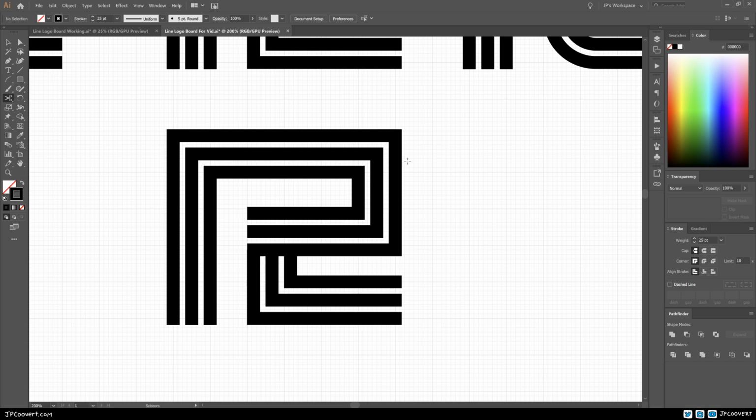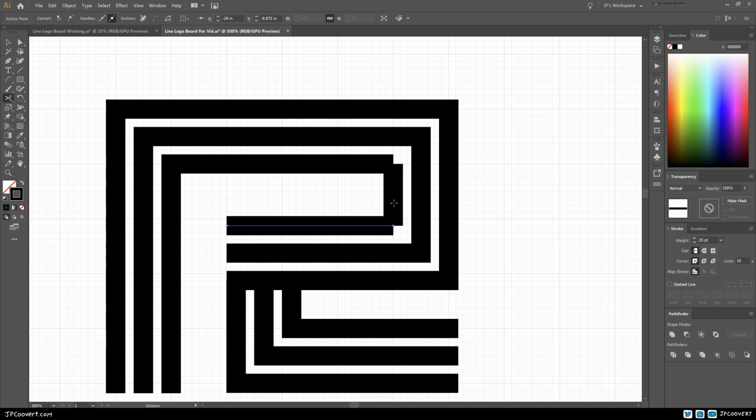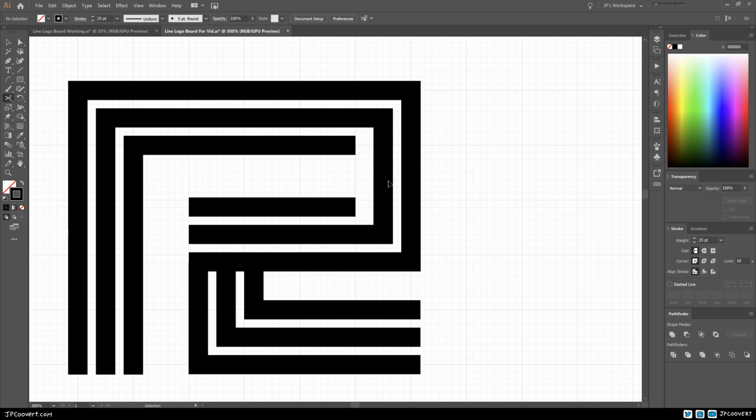If you have the scissors tool and you don't want to go back and forth between selecting the scissors and the direct selection tool, while on the scissors tool you can hold down Control and it'll turn into the selection tool. So we've selected this path and now we have the scissors tool and we can snip it. So I'm going to snip these 2 pieces, and you can see there's a little visual glitch that happens in Illustrator, but if we just zoom in, it'll fix it. And now, while holding down Control again, I can get the selection tool, grab this line, hit backspace, and now maybe you can see where we're going with this.